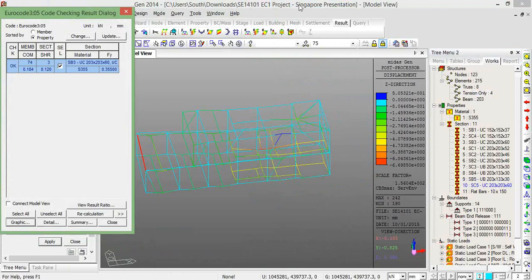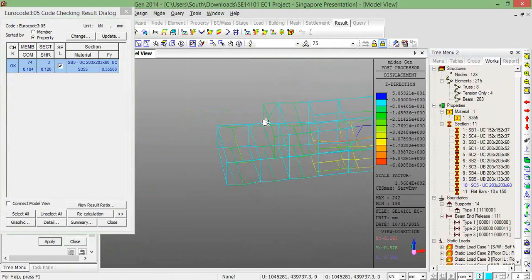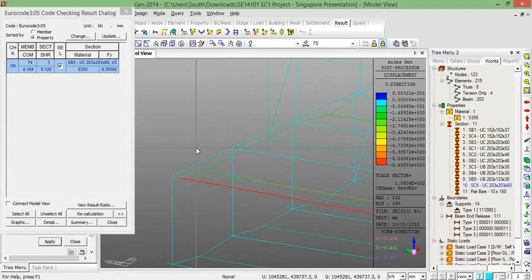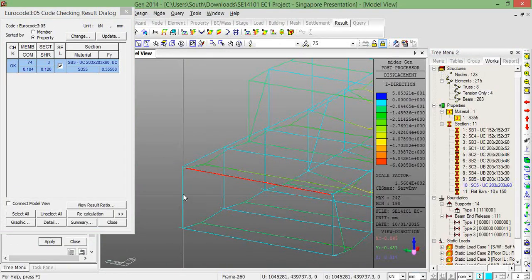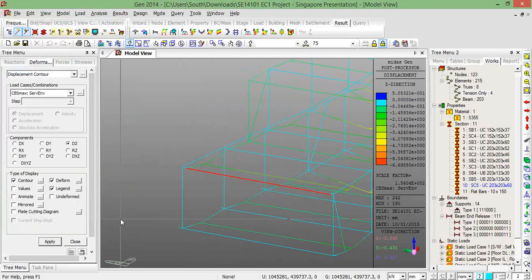The client didn't want that. He particularly wanted them to be in as small sections as possible, preferably having corners and any fixed moment connections being prefabricated, so you're just bolting splice connections at mid-span, or 1-meter sections into beams. So we had to ensure that these connections would be adequate.